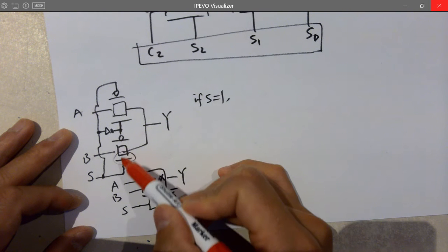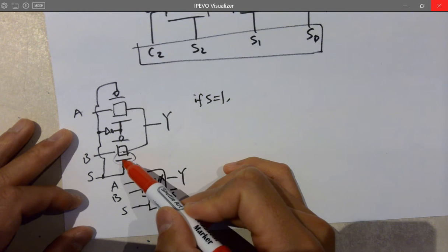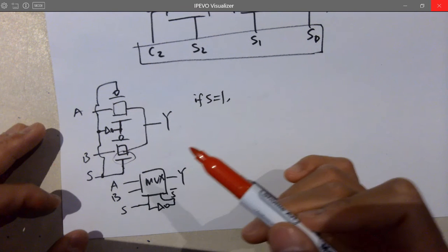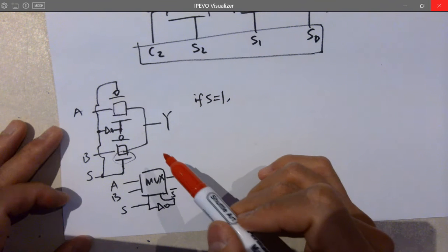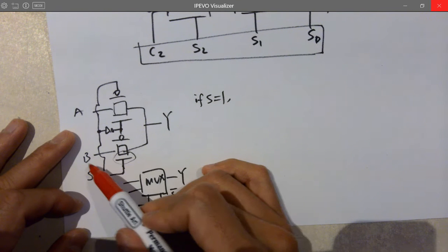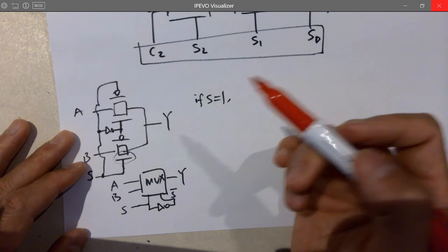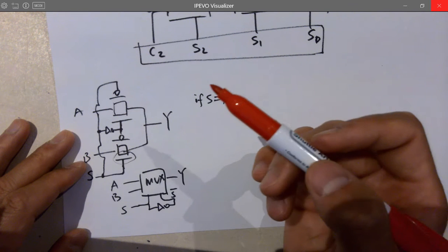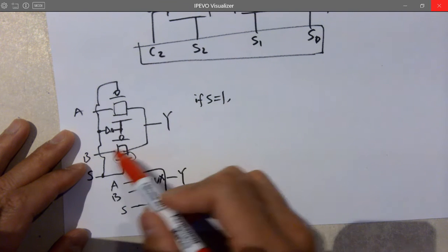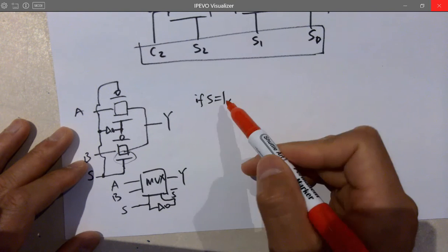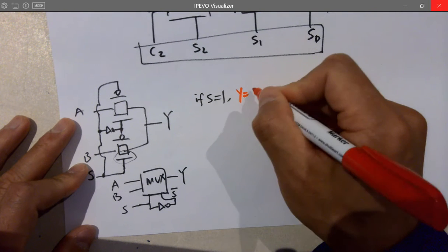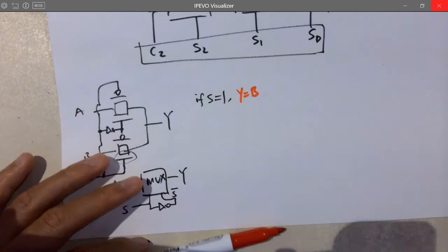Since you have two transistors, one PMOS and one NMOS, and PMOS is good at passing ones and NMOS is good at passing zeros, whatever S is and whatever B is, it's a digital circuit, so there are no intermediate values. It's going to be 1 or 0, so it's always passed to Y. Is that correct?